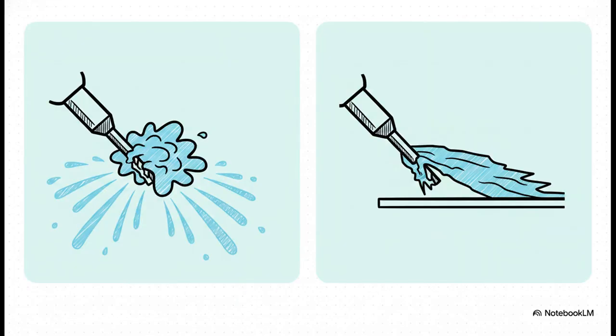But hey, even within the exact same difficulty tier, materials can frustrate machinists for entirely different metallurgical reasons. Take 1018 carbon steel and pure copper. 1018 steel is notoriously gummy. It's super prone to creating a built-up edge on the tool, which means you absolutely need high-pressure coolant.